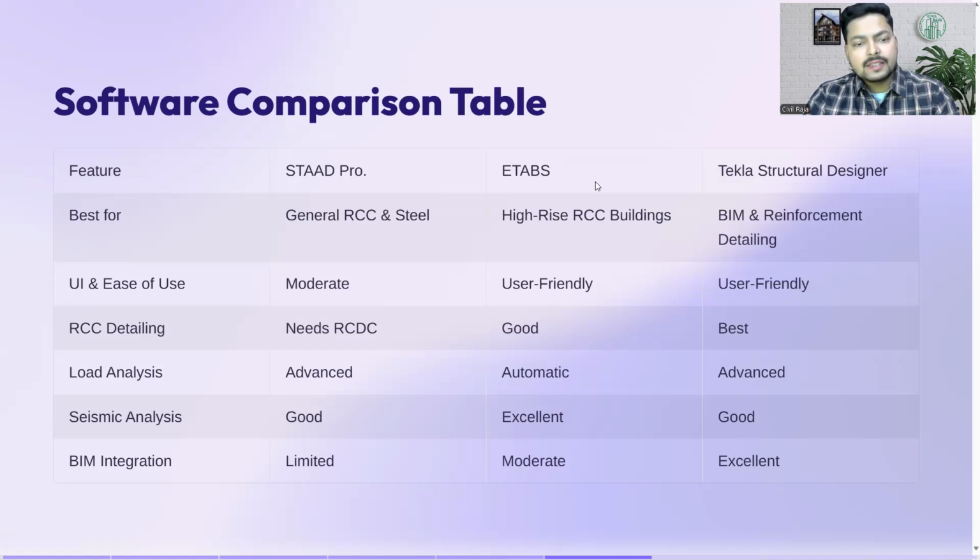Then for the load analysis, STAAD Pro is very advanced. In Etabs, you have automatic load combinations, and in Tekla Structural Designer, it is again advanced in load analysis. Now in STAAD Pro, seismic analysis is good. In Etabs, it is excellent, and in Tekla Structural Designer, it is again good. For BIM integration, STAAD Pro is limited, Etabs is moderate, and Tekla Structural Designer is excellent.